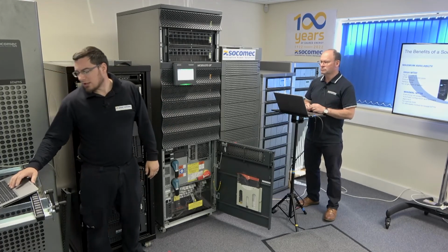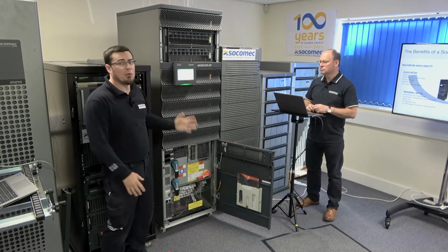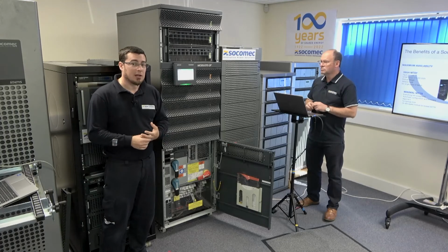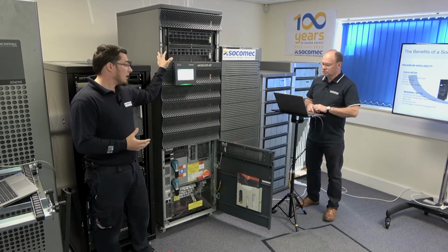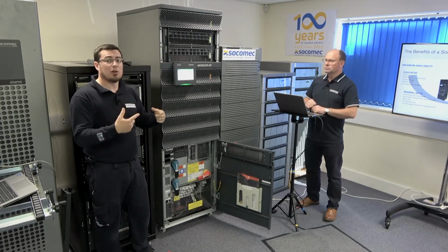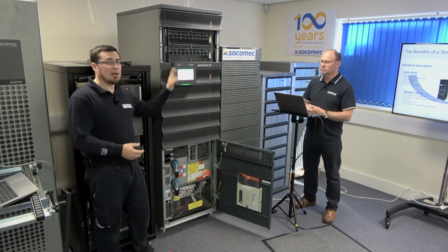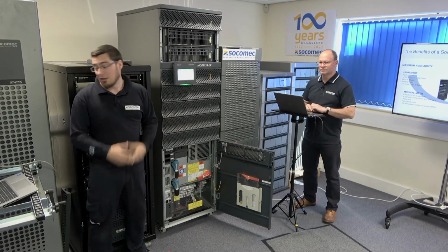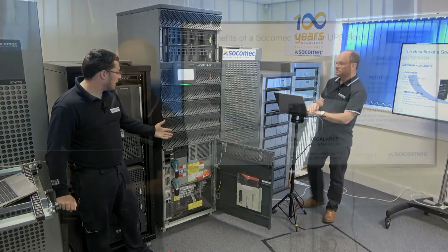Something about firmware updating for the whole system. So yes, the firmware is held on the control board, which does the auto firmware alignment. If you did need to firmware update the whole system, you would need a Socomec engineer to do that, but again, we can do that whilst it's all online. So as long as you've got redundancy, an extra module, we will take one module off at a time. It does the firmware update, puts that one back online. Once it's happy, it does the next one, and then it will do the bypass, control and display. So you don't have to actually go to bypass even for doing a maintenance firmware update that way, which is superb.